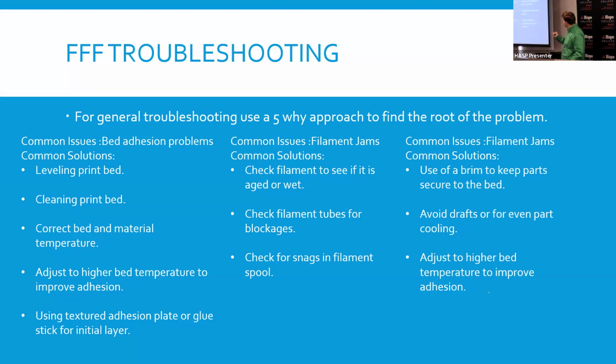Common issues, common solution. Or I'm sorry, not filament jams. That's supposed to say warping. I apologize. So use of a brim to keep parts secured to the bed. So those platform additions, such as your skirt, your brim, and your raft, are gonna keep it glued down. Like we talked about before.